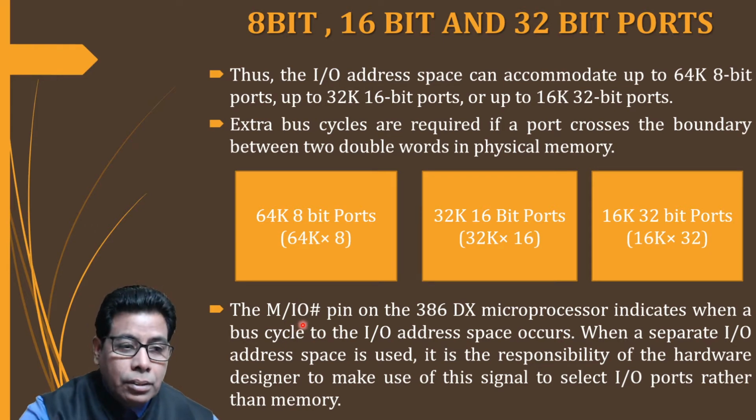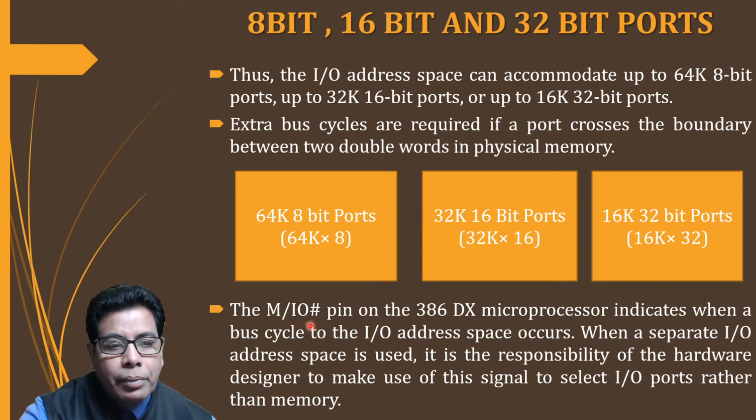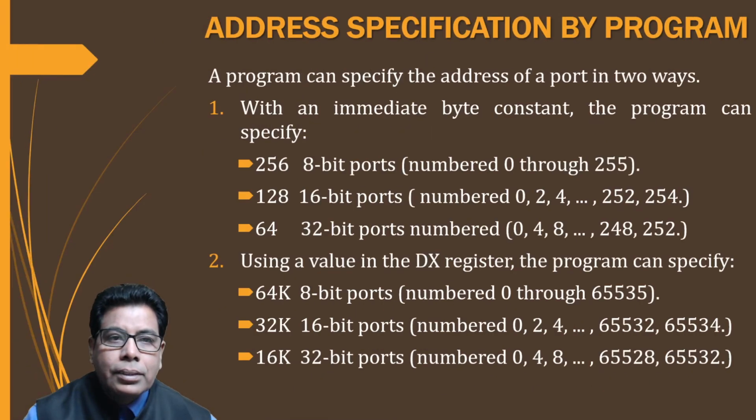So this signal, M/IO#, will separate the memory and I/O. If the designer uses this for selecting the I/O ports, then he can use the separate I/O space. Then let us go further: the address specification by a program.